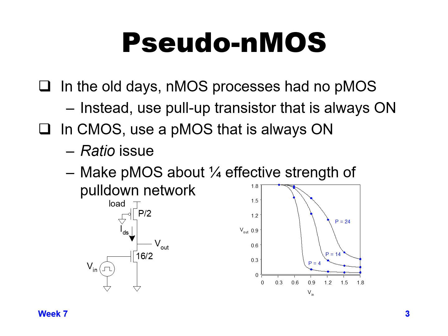And when P gets to size 24, you can see it's only getting down to 0.3 or maybe 0.4 volts. And so as the PMOS and NMOS get closer to the same drive strength, you can't pull nearly as close to ground as you would like to in pseudo NMOS logic.